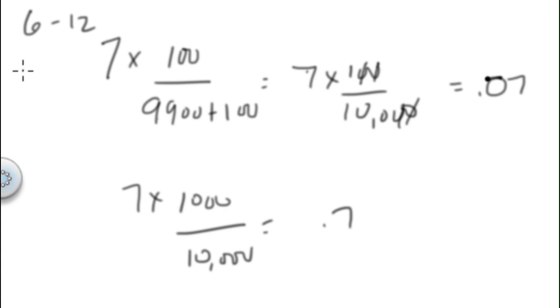Okay, so they want to know the 10K, across the 10K. So here we are. We're now looking at a dependent source, and we've got a voltage of 1 millivolt, and we say, okay, now that through a 100 ohm resistor gives me what? What's the current? 1 millivolt times 100 is equal to